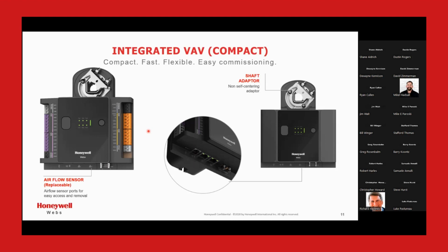The Spyder 7 is still part of that same family. They're still kind of running the same processor style, same memory, same engineering style, but they have more memory. They have more capability physically under the hood. They're beefed up, and they are available with variations of BACnet over IP as well as MSTP. So you'll be able to order whether you want the IP version or the MSTP version. So that's the number one difference between a 5 and a 7. 7s have got more memory, they've got more power, but the big difference is right here. Only the 7 family is available with an IP variant.